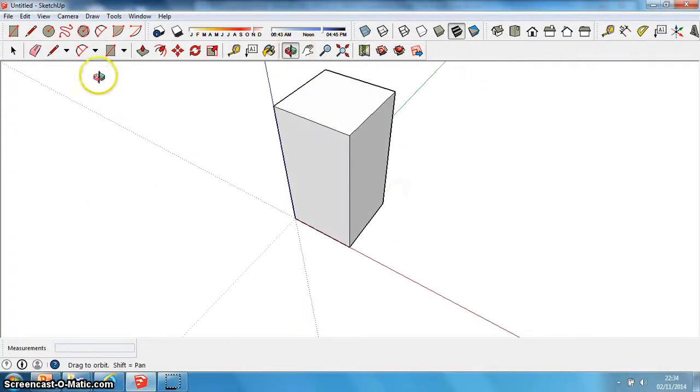Okay, so next thing I'm going to do is I'm going to treat this three-dimensional object as almost like a piece of clay that I'm going to carve away shapes from. So first thing I'm going to do is set a line parallel to this edge, to give me the backrest of my chair, and I'm going to carve the rest away. Okay, so I'm just going to use an arbitrary measurement just for this. Click once, drag down.